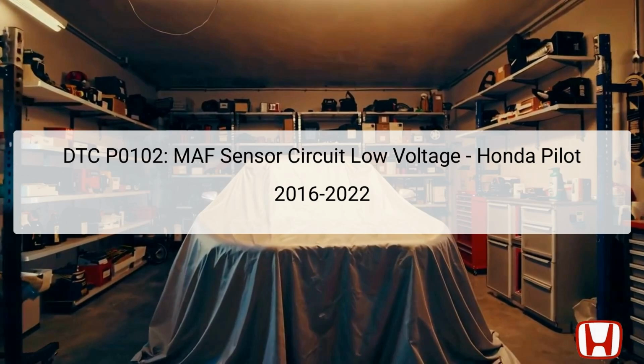The Diagnostic Trouble Code, DTC P0102, indicates a low voltage issue in the mass airflow MAF sensor circuit. This can severely impact the engine's performance, as the MAF sensor is crucial for measuring the amount of air entering the engine's intake. Proper functioning of the MAF sensor is vital for optimal fuel injection and emissions control.